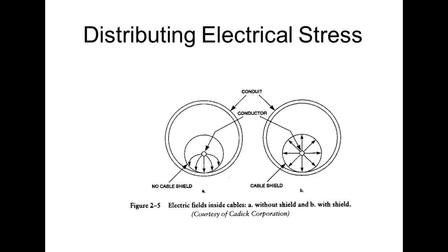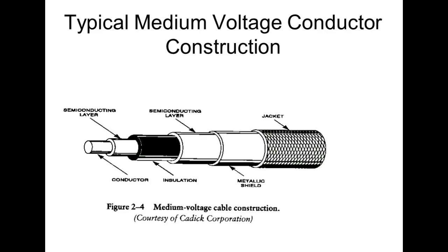Now, if the insulator is rated at 600 volts, that's 600 volts all the way around. It should be distributed equally around the insulation. Does that make sense? If I move all that electrical stress to one side of the cable because we run it close to another chunk of metal, then we're going to arc through the insulator.